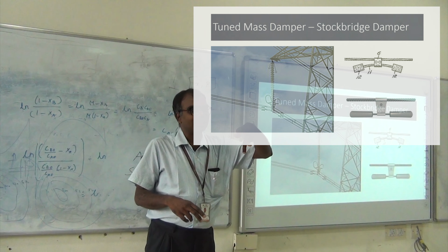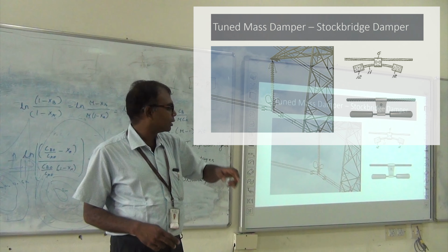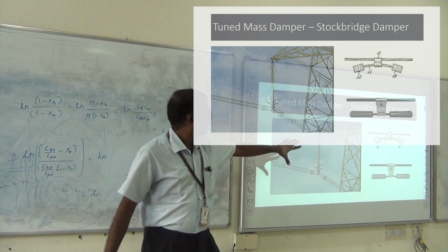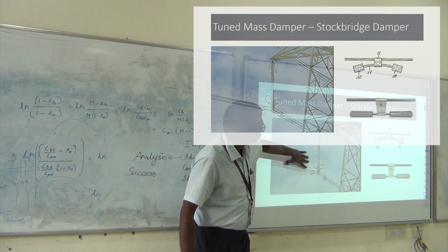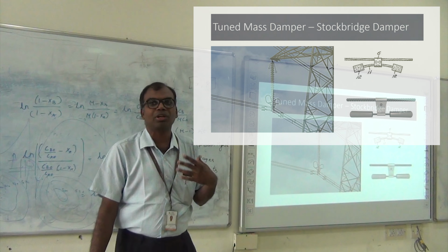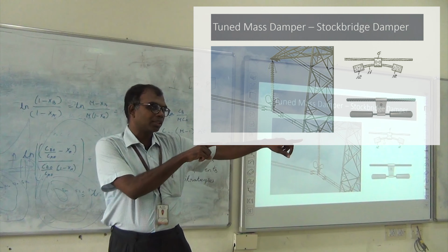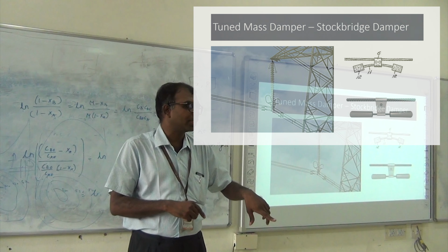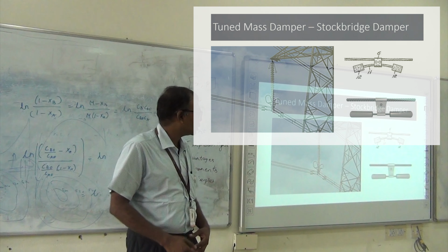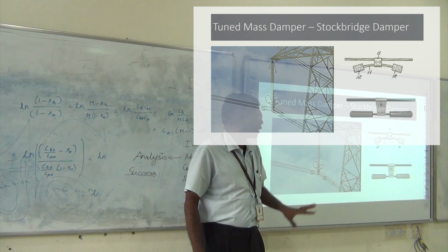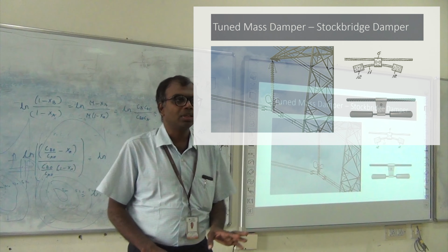Okay, and this is just like a clip. It just fits on top. It protects the insulator string. It also protects the cables from snapping. We were talking about fatigue. So suppose it is the low frequency continuously oscillating, it is again going to cause damage to the cable or to the structure or to the insulator string. We don't want any of this to get damaged.